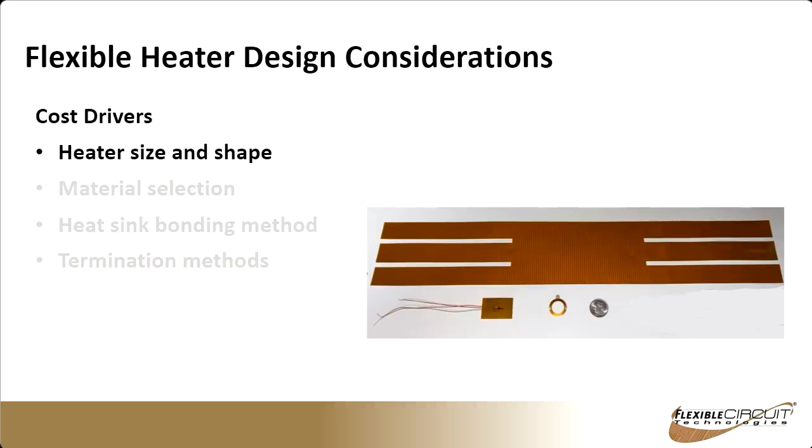Now we're getting to cost drivers a little bit. As we talked about earlier, heater size and shape can have a big impact on the cost. If you have something that's very, very large, sometimes it's better to go with 2 smaller heaters that will fit a little bit better. And I'm going to go into the way these are processed in a little bit. Since these are done on panels, we typically want to try and fit as many parts as we can on a panel and optimize every square inch of space and throw as little into the garbage as possible for scrap. And if you have something that's very oddly shaped or very large, it's taking up a large chunk of the panel, it can have a huge impact.